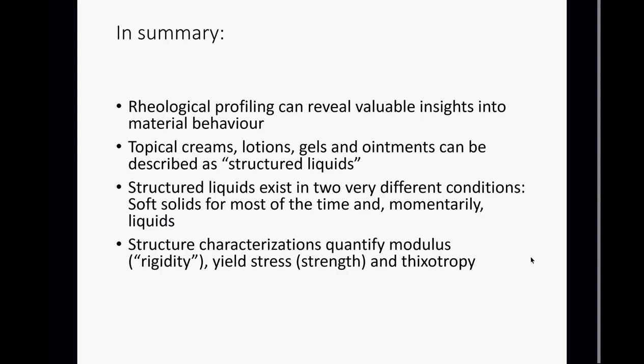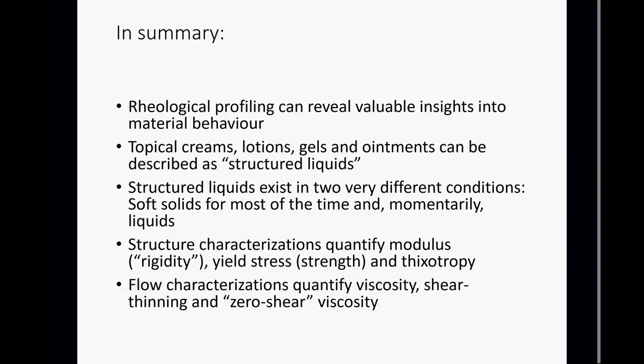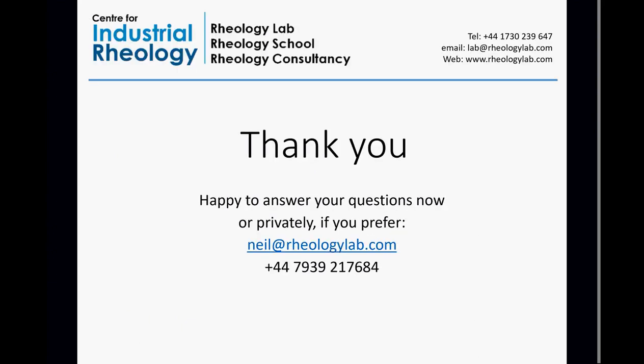When we're characterizing structured liquids, we're interested in the rigidity of the structure and the strength of that structure when it's present. We're interested in the viscosity of the material when you've broken that structure. And then we're interested in the rate of recovery back to that initial structured condition when you cease applying any shear to it. Okay, so that's all for today.